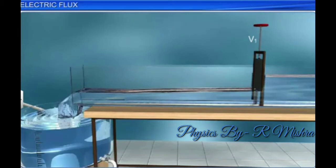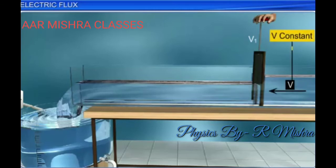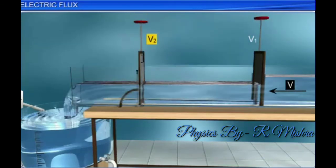To regulate the discharge, we increase the open area of the regulating valve, V1, assuming that the velocity of flow of water upstream remains constant. Let us install one more valve, V2, downstream to V1. V2 is pivoted to the bottom of the channel. Valve V2 can swing about a horizontal axis, which is perpendicular to the direction of flow of water. This completes the apparatus. Now for the experiment.